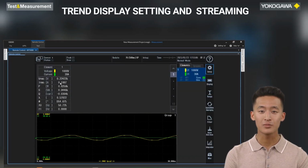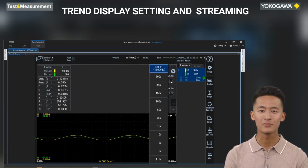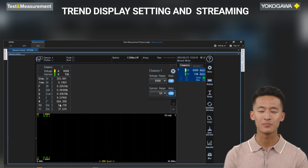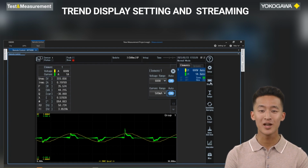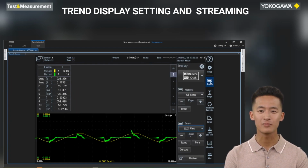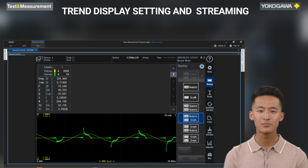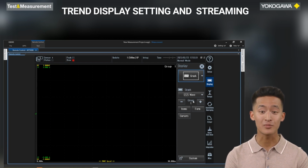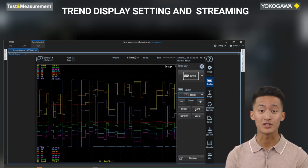Let's first do the measurement settings like appropriate voltage and current range selection, etc. After measurement settings, click on the display icon. It will open up a sub-window in which select display and from the drop-down select graph. Click on the drop-down under graph and select trend from the available graphs. Now we have made the power analyzer into trend display.